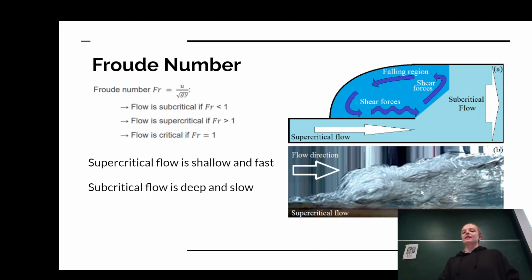We've got this thing called a hydraulic jump. And this is where our flow is critical, and it shifts from supercritical to subcritical. And if you have to remember one thing from this course, it should probably be that you can't go from supercritical to subcritical without one of those hydraulic jumps.